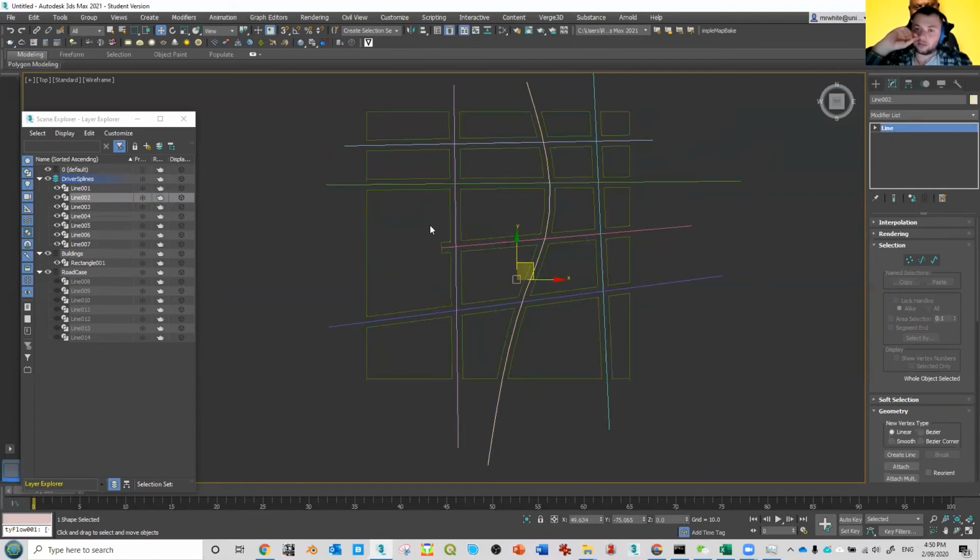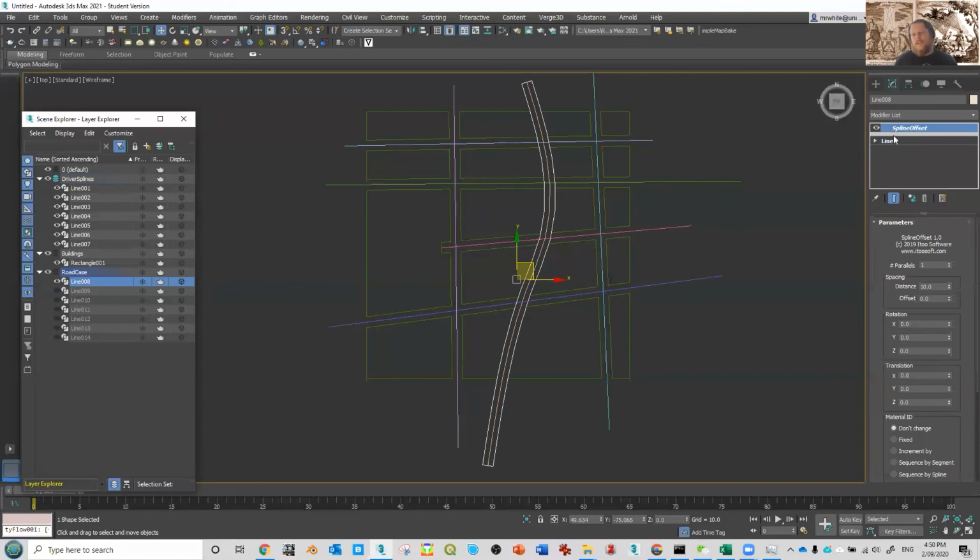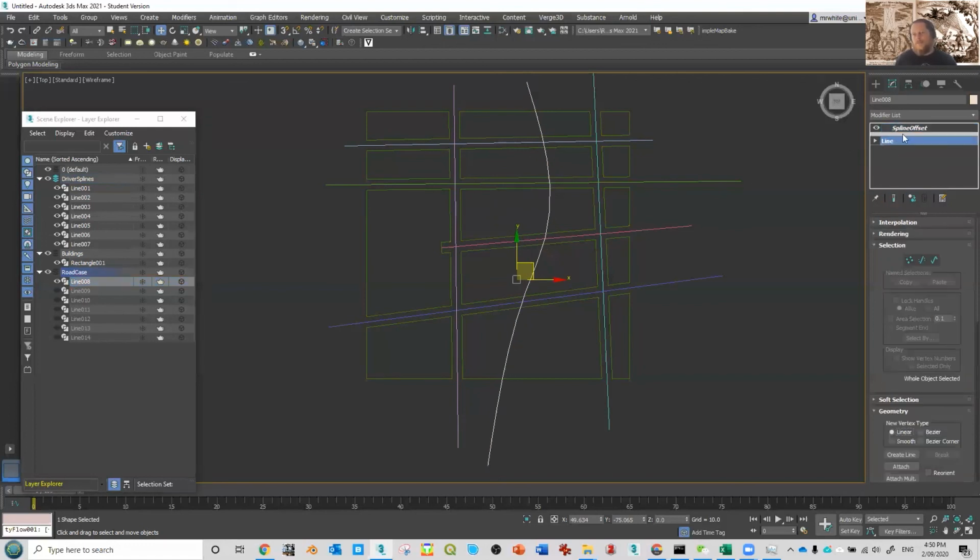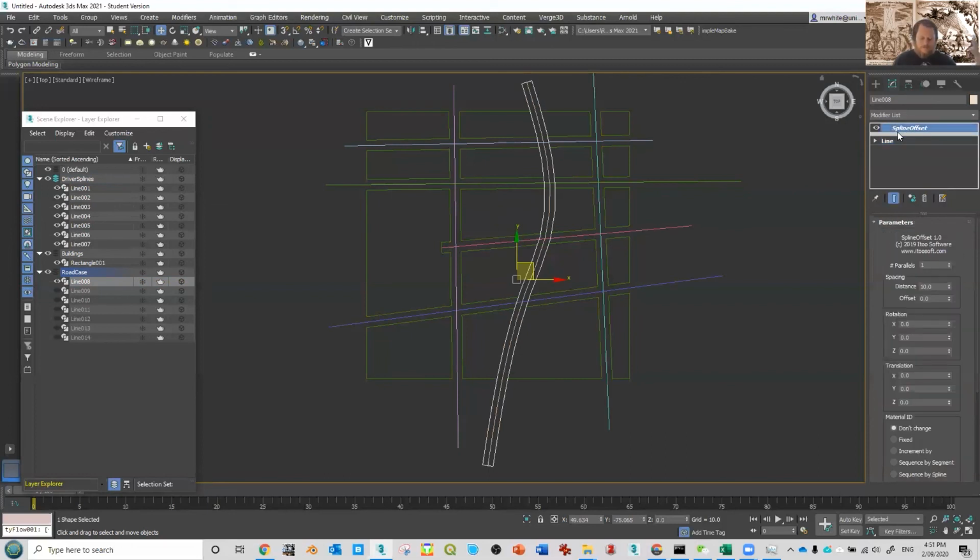When you copied them, did you do them as an instance? As a reference. Okay, there we go. Because if you do them as an instance, everything's identical. Whereas with this, if I turn this guy on, you get this grey line. Below that line is instancing, and what happens above is specific to that referenced clone.